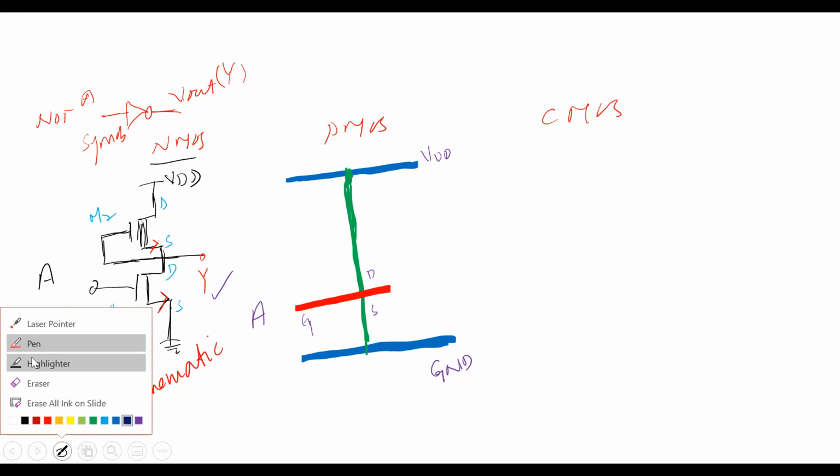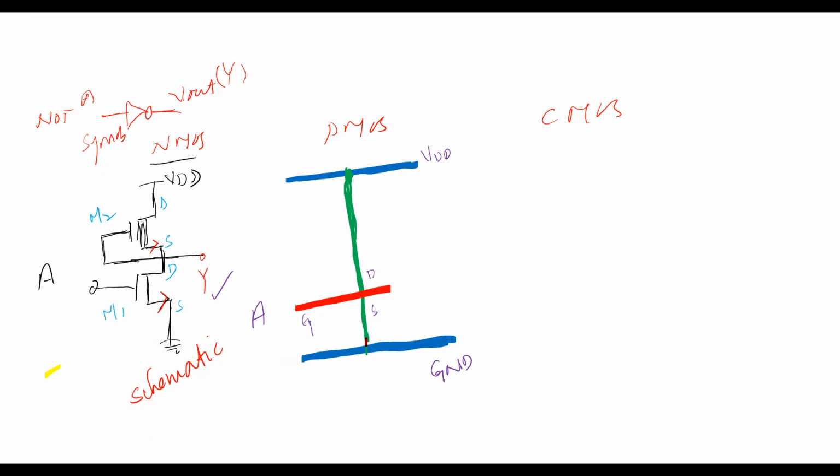So I will put a black color contact. So here is one contact. Got my point? Yes, sir. Similarly, on the top there is a VDD. One metal layer and another N diffusion are both joined, and because these two are dissimilar layers, you need to put the contact cut here also. Then the electrical contact is established.